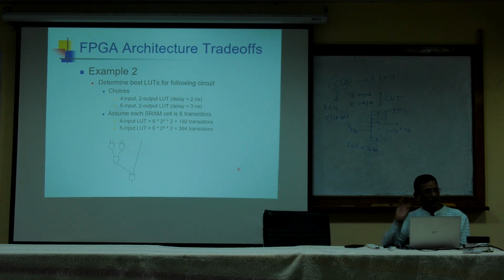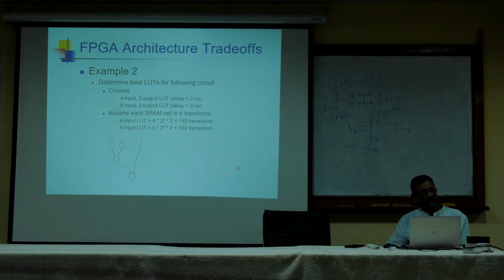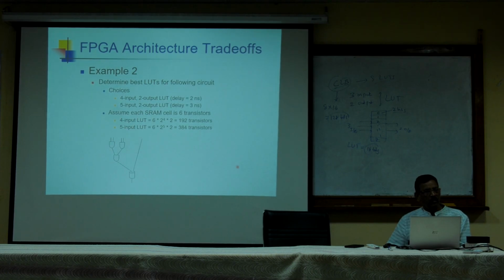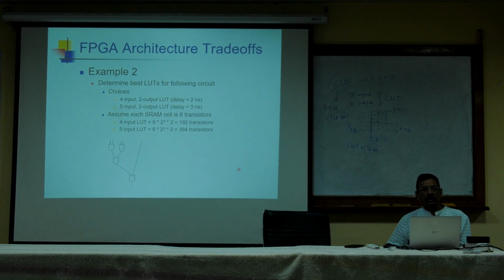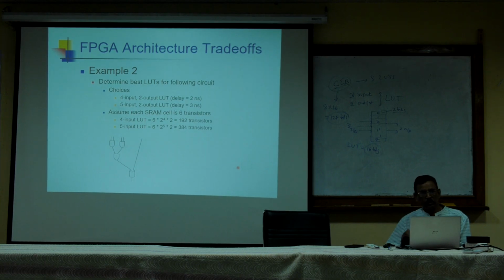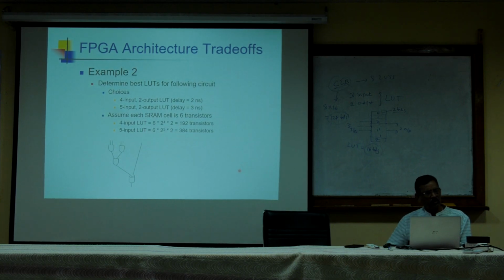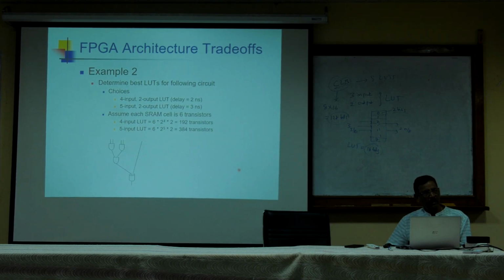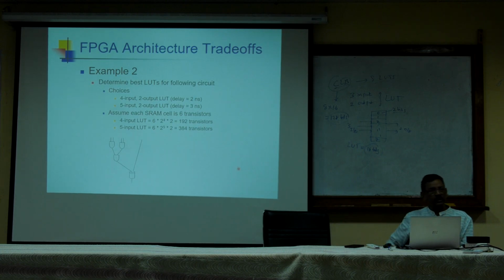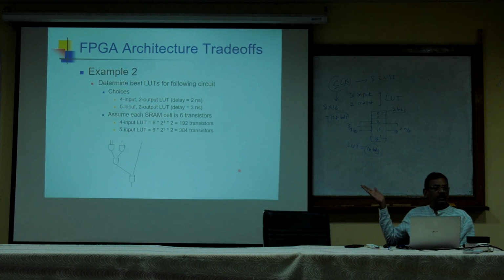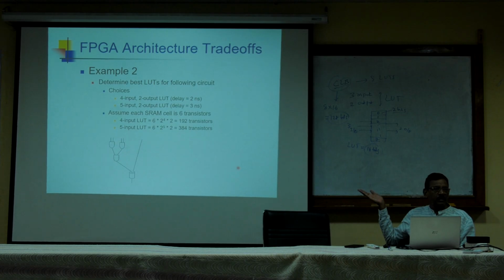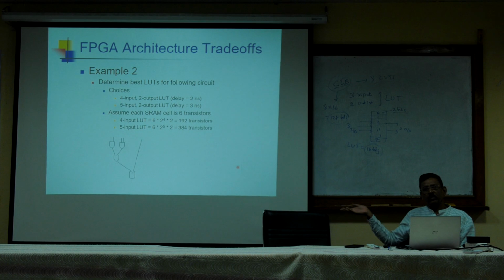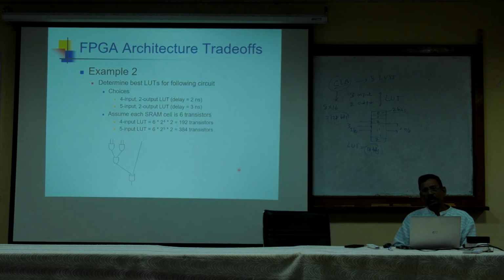If it is a 5 input LUT, how many LUTs are required, 1 or 2? With a 5 input LUT, one LUT is sufficient. How many inputs are there in this circuit? 5 inputs only. So one single 5 input LUT is sufficient.